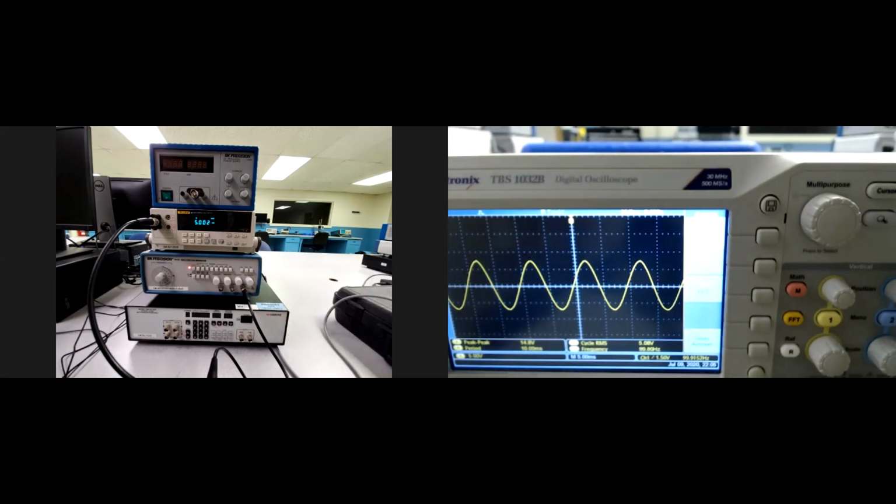Okay, and I'm gonna make sure that I have the right frequency. Okay, close enough. Now, for step number 5, you're gonna write down data from the multimeter. We have 99.91 hertz, and we have an amplitude of 5.00 volts RMS. Those are coming from the multimeter. That's the raw data.